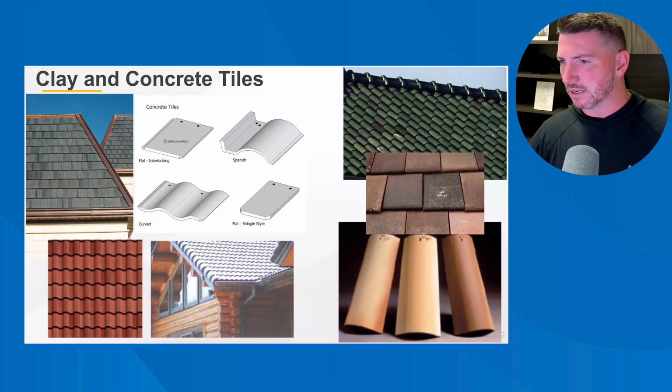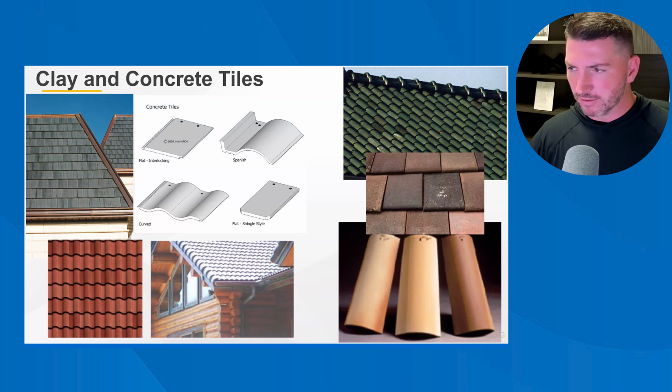You've got that glazed clay tile on the upper right, looks like a concrete tile on the upper left. And you can see those concrete tiles, you've got that same Spanish look as the clay tiles. You've got corrugated or curved ones, flat ones. They make them in all different shapes and sizes. I think the main thing is, unless you're sure, I really wouldn't walk on them. Clay tiles, I would never recommend that you walk on. They're dried out a lot more than concrete tiles when they're made, and so they're a little bit more brittle, much harder to walk on successfully. I wouldn't really recommend it.